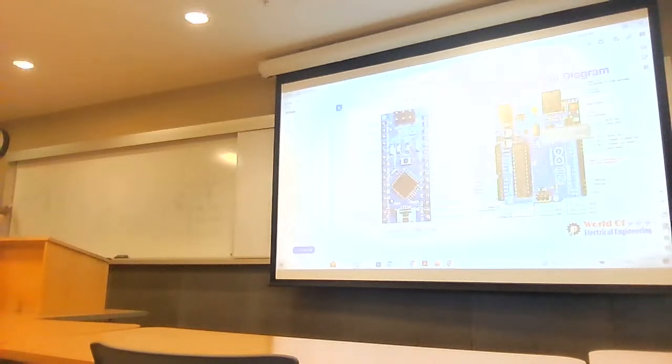And here you can see the reference. This reference is nothing but a crystal oscillator, and here we have the VCO. This VCO can provide high level frequency. So how can we design it? First of all, it's clear, right? Why do we need a PLL? We need a PLL to generate a gigahertz level frequency, as well as we can change our frequency depending on the input voltage. We can produce several bands of frequency. In this projector, there is also a PLL.